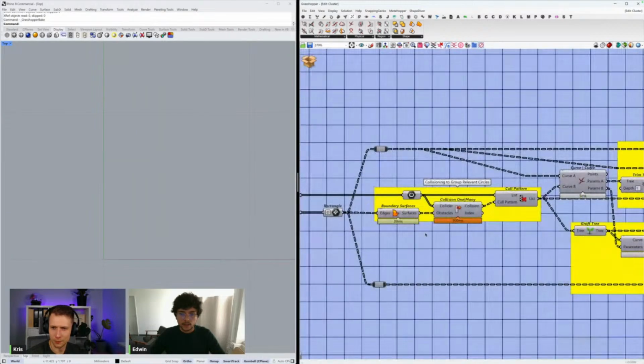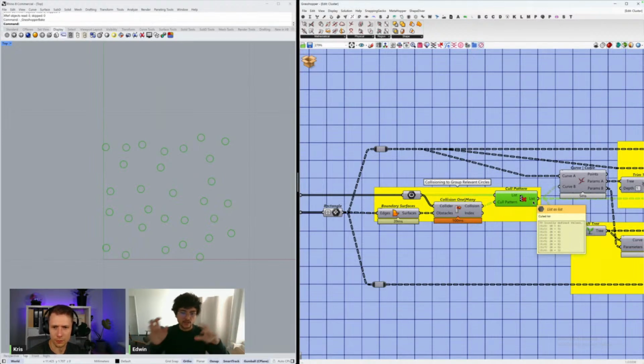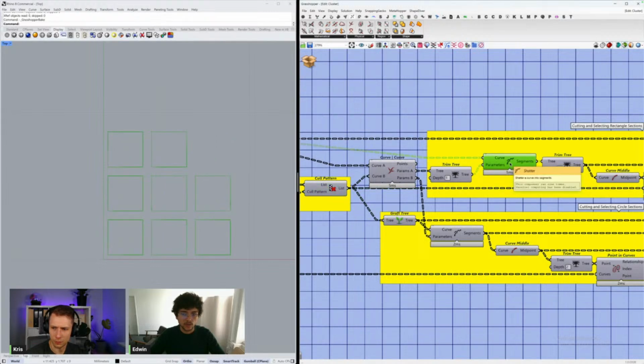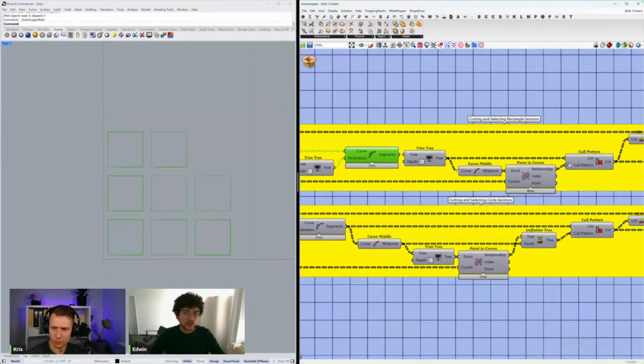And then I'm doing the same check of collision. Then that groups again in branches my circles to the branches which are relevant for each of the rectangles. But then I'm using simpler operations. Before I was still using the region difference operation. Now I don't need that. I could just simply do a curve intersection, then do a shattering. So I shatter my curve, and then I do a containment check.